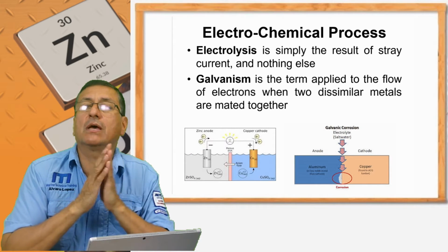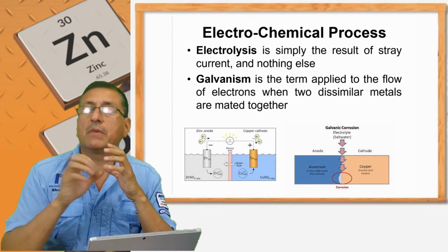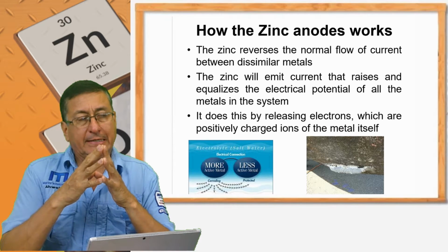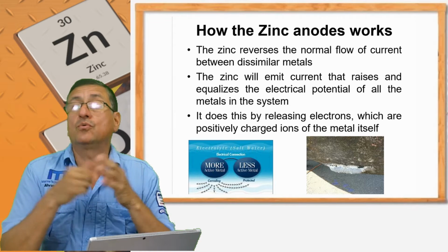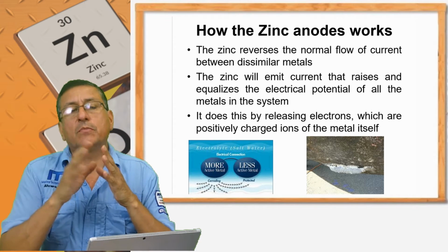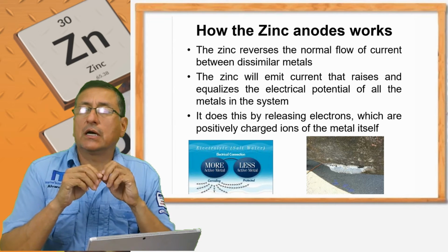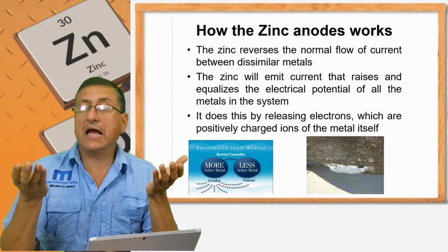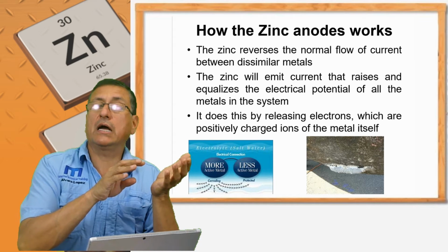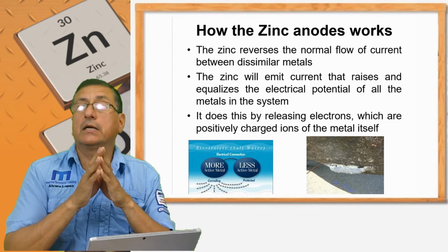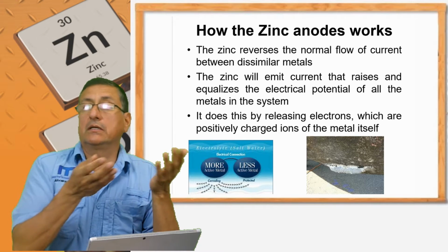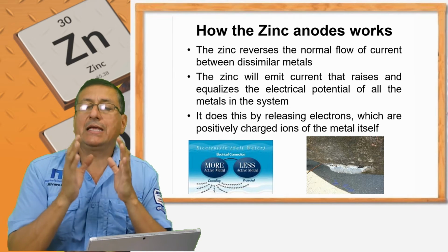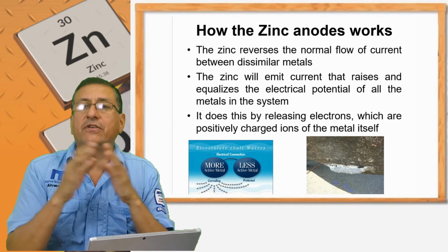You remember the previous episode when I explained the procedure with the amps method or with the volts method to check where the leaks are. Now we are going to try to understand how the electrodes work, why some sacrificial anodes are better in some conditions and not good in others, and in what case each type of sacrificial anode is recommended. We are going to check exactly in each situation which sacrificial anode is recommended.